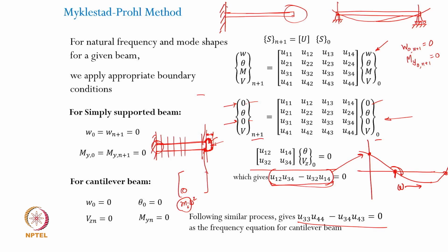If properties like the cross-sectional dimensions are continuously changing, as I said, that is very typical of a cantilever beam, and of the blades on gas and steam turbines. You can discretize this into several segments, and each segment's cross-sectional properties can be assumed constant in the segment, right? Now there would obviously be inaccuracies, because depending upon how wide the segment is, your properties are going to be an approximate estimate of the entire segment, because you are averaging it out, right?